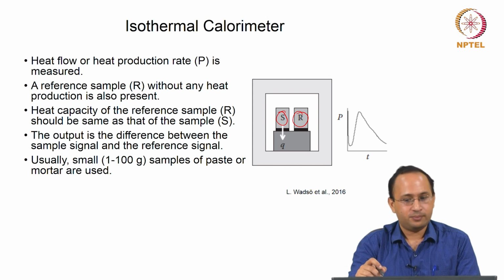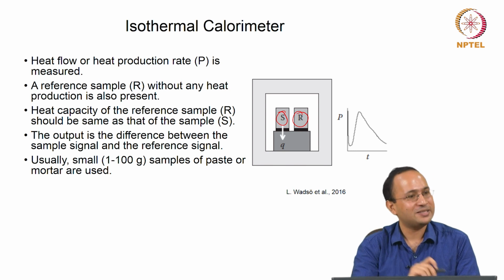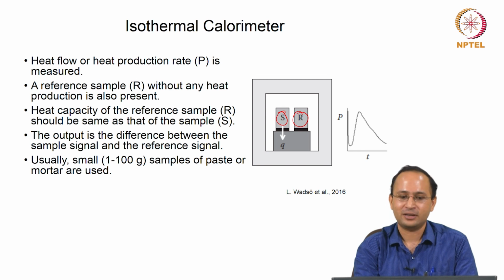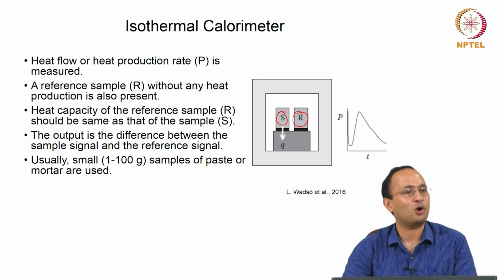Important point to keep in mind is the heat capacity of the reference sample should be same as that of the sample. That is very important. Heat capacity of the reference should be same as that of your sample, but it should not release any heat. So for an example, you can take quartz or water as a reference, right.